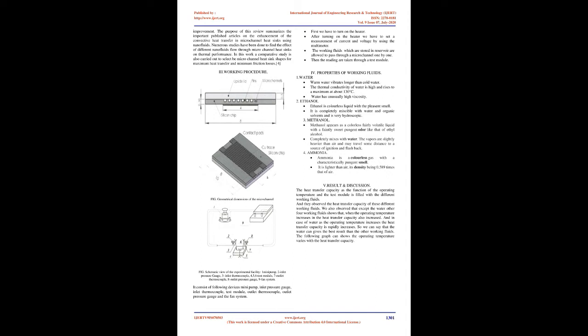Afzal Hussain, Kwang-Yong Kim et al. state that the present study deals with the numerical optimization of a microchannel heatsink with the help of surrogate analysis and an evolutionary algorithm. Three design variables related to the microchannel depth, width, and end width are chosen, and their ranges are decided through preliminary calculations of three-dimensional Navier-Stokes and energy equations. Objective functions related to heat transfer and pressure drop, i.e., thermal resistance and pumping power, are formulated to analyze the performance of the heat sink.